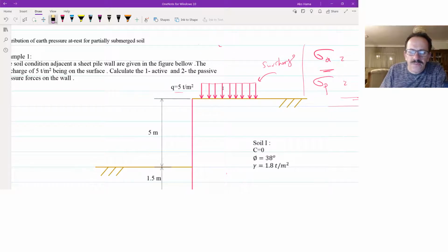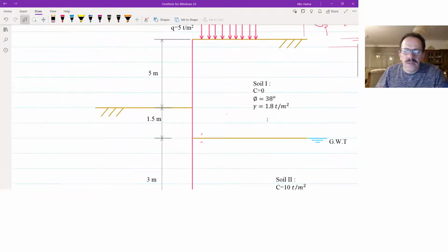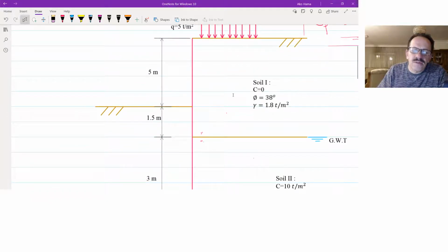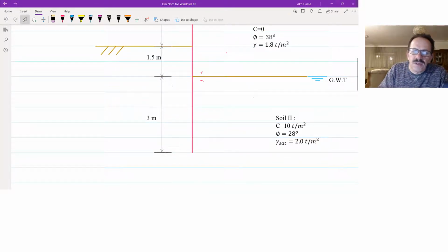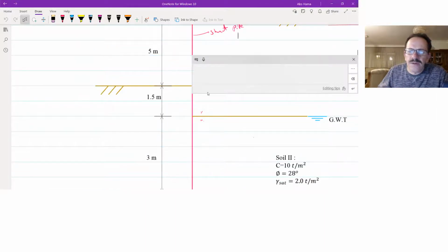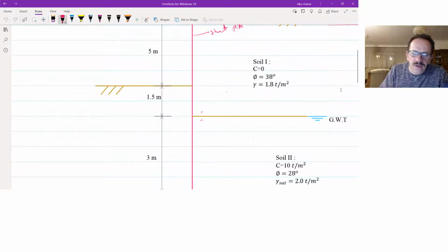Now if I have this and we want to excavate 5 meters depth and work here, what should we do? We have to use a sheet pile. This is called a sheet pile, or retaining wall. Now, before that, we excavate 5 meters, and the sheet piles tell us that at 1.5 meter depth from here, there will be a groundwater level, so we have to be careful about this.